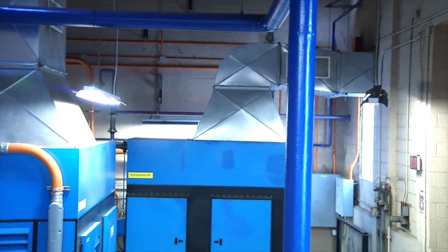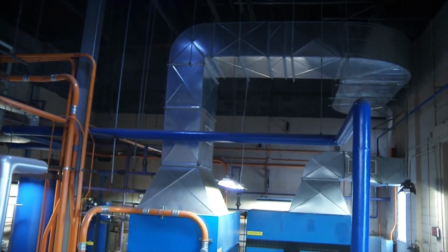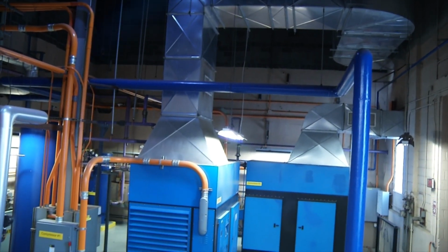I have to say here that this worries some people because of the humidity in summer. Bringing it in from the outside will cause too much water in the air and will create problems for some of these rotary screws. But personally, I've only seen that at my home base, Rutgers University. They duct their exhaust outside but use compressor room air for the intake.